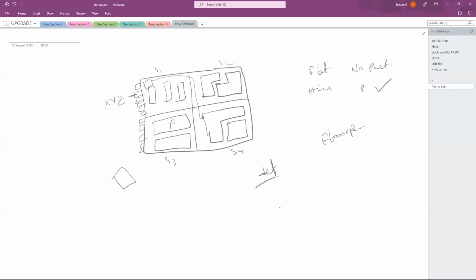You'll be getting the placement DEF or floor plan DEF, meaning the output format of the stage is a .def file, which holds the information of that entire stage. If you perform your floor plan, your output will be floor plan .def. If you source this particular DEF, it is enough to show you the physical context of every cell. You don't have logical context. If you need logical context as well, you need the logical libraries. So you have only the physical floor plan .def.